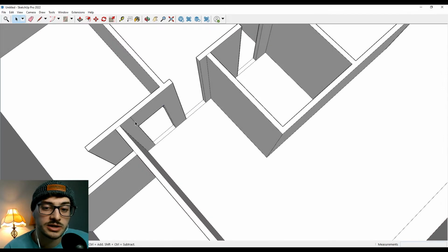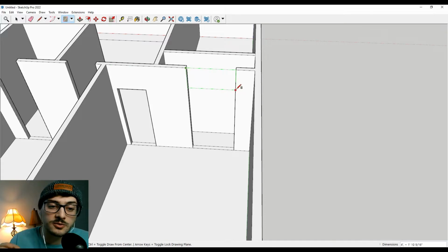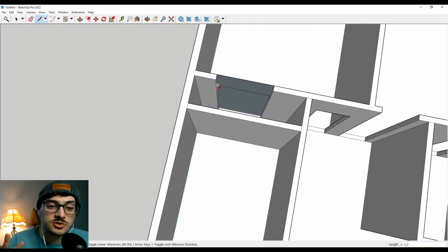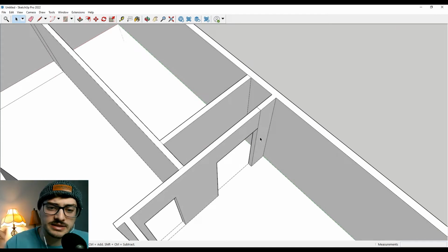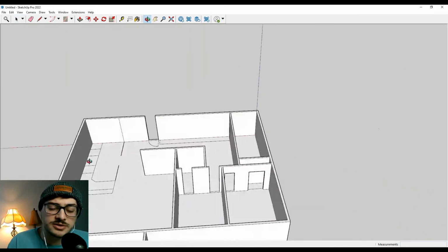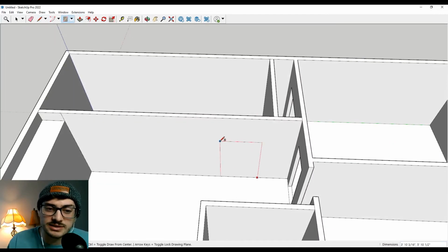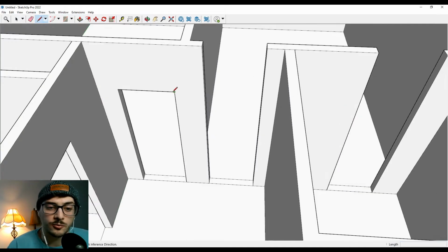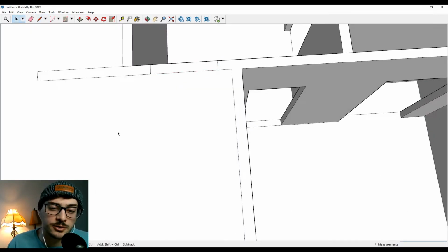You specifically want to click on the walls that you made with width. And here's where it's important. If you make walls that do not have width, like they're just lines, then once you extrude everything up 9 feet, you can still work with it, but you're going to need to delete the ceiling out everywhere, because now it's going to try to generate a roof over it because it thinks it's extruding a solid cube of material, because it doesn't see the walls as a different subject than the room. So when I say extrude, that's the push-pull tool. It's basically turning things 3D that were 2D.